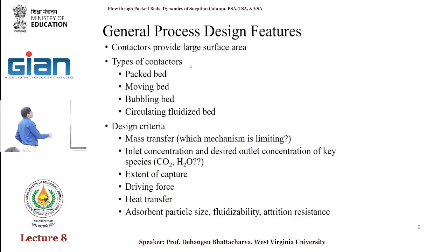The other design criteria that you need to consider is the extent of capture, that is, how much you want to capture here. Then you need to consider what your driving force is. The other problem is the heat transfer. In today's class, we'll be discussing quite a bit about the heat transfer for these beds. And that is in the bare bone model that you will have in Aspen Adsim. A lot of these things will not actually be accessible; it will not give you access to doing a lot of these things.